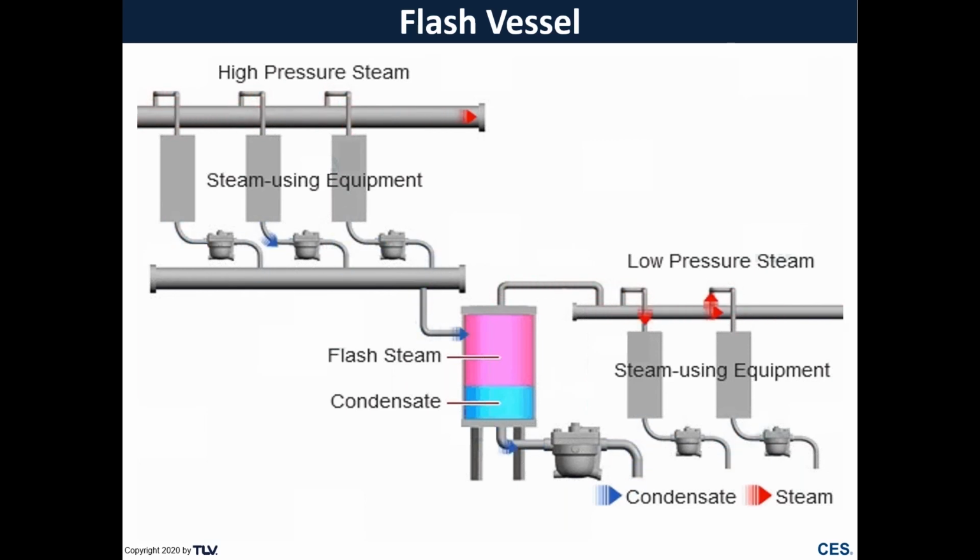It does as we described before, separates the flows. We can get rid of the condensate and recover it somewhere else. And then the now low pressure steam can be used in our low pressure steam header to supply our lower pressure steam using equipment.